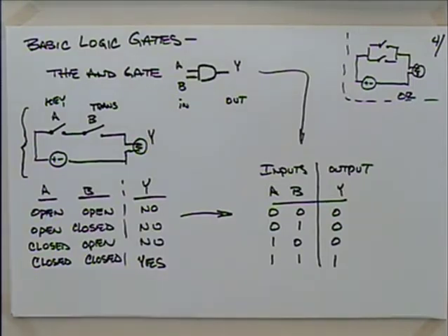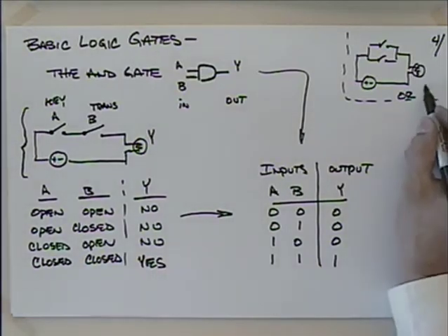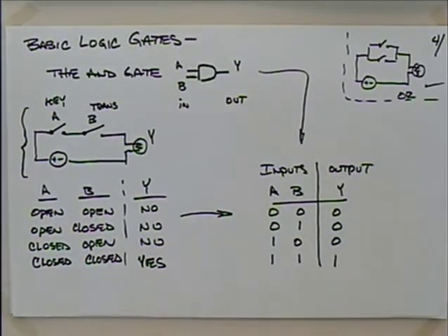Yeah, because you want the transmission to be in neutral or the clutch to be pushed in, whatever transmission you have, and the key turned on. You wouldn't want this arrangement, would you? Where you could either start it in gear with the key, or you could start it without the key just by pushing in the clutch. That would be a wrong arrangement, wouldn't it?